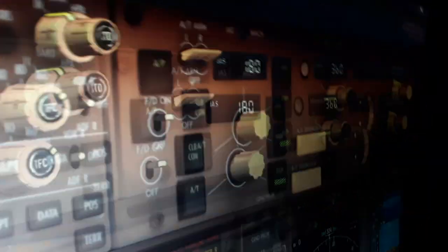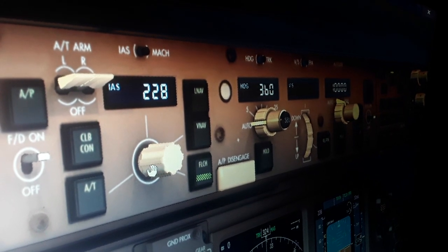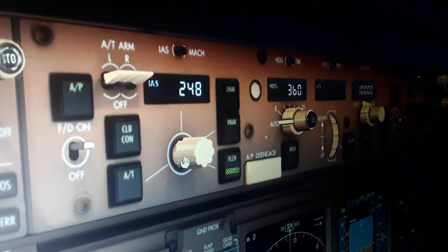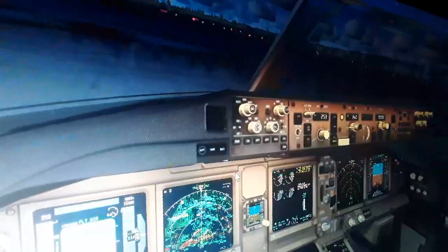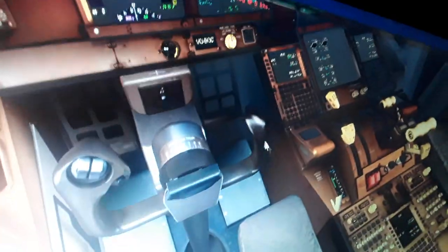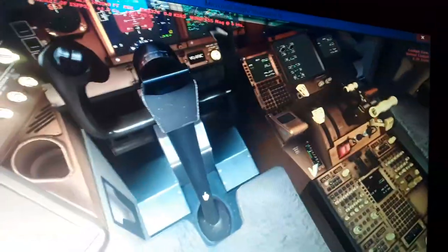So we have also the auto thrust to disconnect here. You will set the thrust automatic like this. This is like arming the takeoff ground switch to takeoff. So we have the parking brakes on, so the aircraft won't move too much. So you can see here again, and we need to make a small pullback.